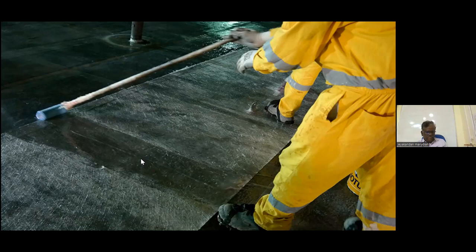Even if severe corrosion is present on the outside, it is possible to apply a double layer of the laminate for a total thickness of 110 to 120 mils. Linings of less than 20 mils dry film thickness will not protect against leakage from outside corrosion. They are recommended only for relatively new tanks with no internal corrosion. Less than 20 mil thin film is for new tanks only.